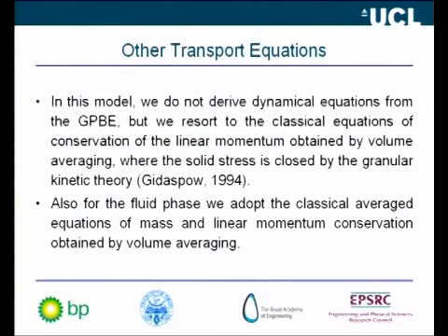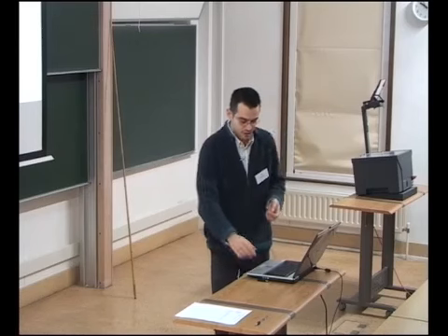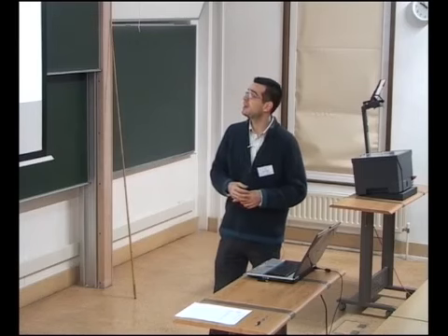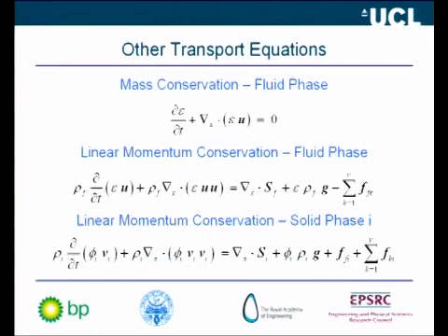Actually, in order to solve the fluid dynamic problems, we also need some transport equations for the momentum. In general, this transport equation can also be derived from the population balance equation if we consider the velocity as an internal coordinate there. Since we didn't do this in this model, in order to close the mathematical model, we use the transport equation from volume averaging, and we close the momentum transport equation for the solid using the granular kinetic theory and Gidaspow's model. For the fluid as well, we use the equations obtained from volume averaging.